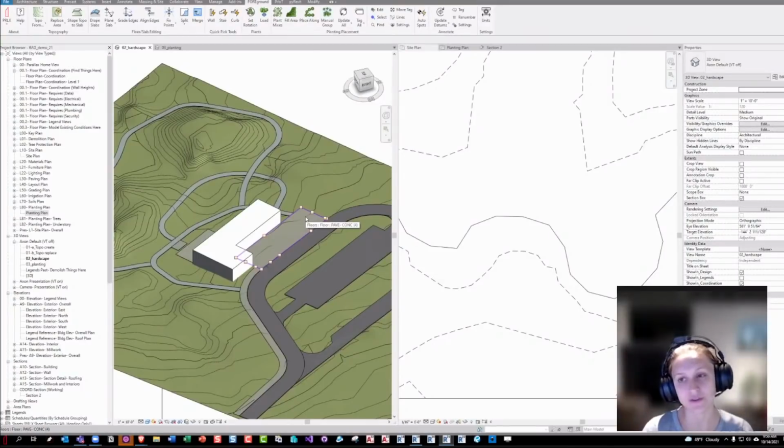This was probably in relation to the drape tool you were just talking about. I think it's a two-part answer, but he asked if the floors relate to the topo, or does the topo relate to the floor? Yeah, it can be either way depending on how you want to do it. They're not establishing any set relationships, so you can still go in and modify the floor, and if you want the topography to follow, you just have to come back afterwards and tell it that. So it can be either way depending on what you're doing.